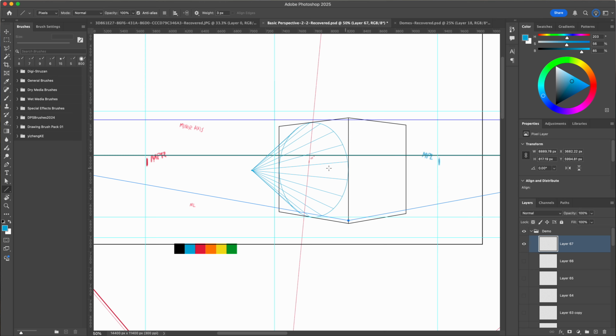And so we were able to use the minor and major axes and both the proportional dividers, so I could get the literal center of this face and the difference between that and the perspective center. And then we were able to use our 90-degree tool, our right angle tool, and our ellipse tool to line up our major and minor axes to get an absolutely correct ellipse along this face.